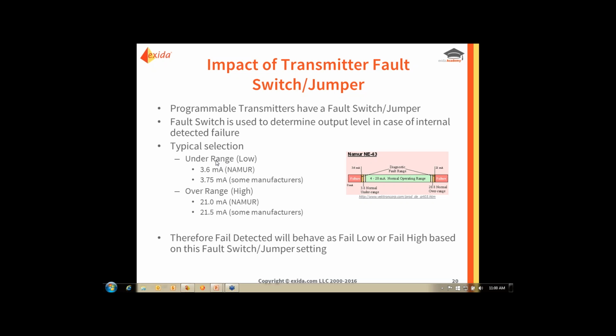Does it have to be in the safety instrumented system, or can it be in the DCS? The standard doesn't prescribe that it has to be in the safety instrumented system. However, you need to consider that this is a comparison where you are claiming credit for improvement in safety integrity, so you really want to have it under good management of change.